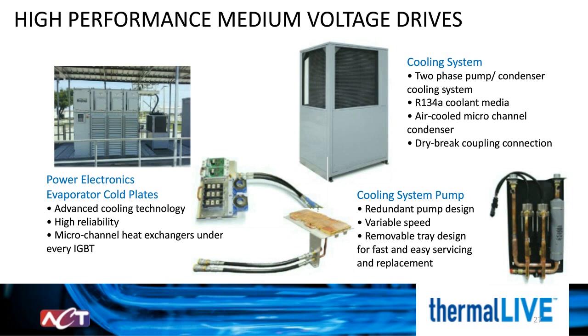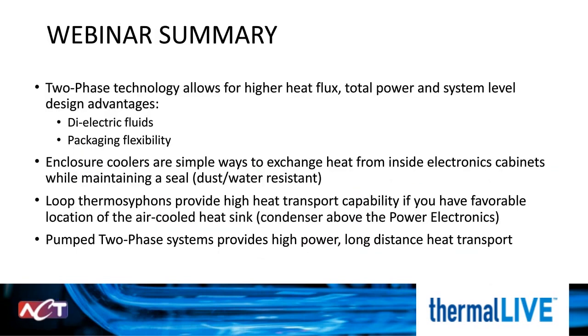In this webinar, we have addressed typical challenges many engineers experience as they design high-power power electronics systems. We've identified that two-phase technology allows for higher heat flux, higher total power, and promotes several system-level advantages, such as the use of dielectric fluids and package flexibility.